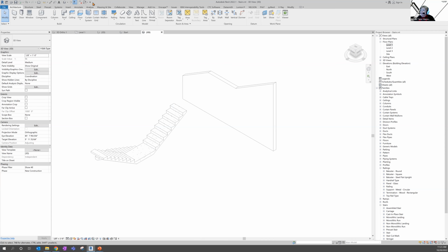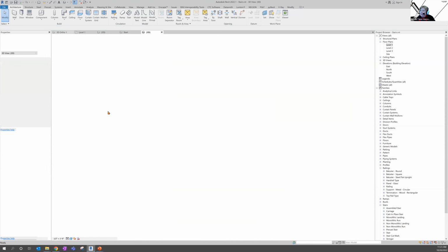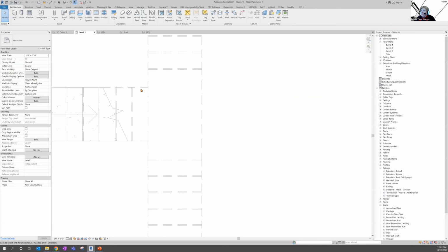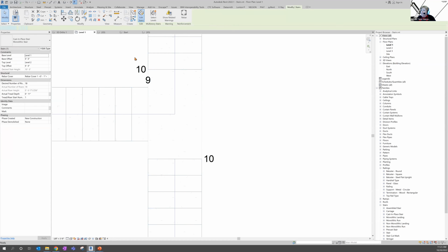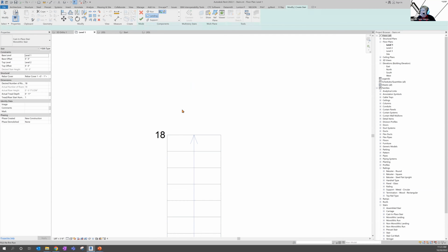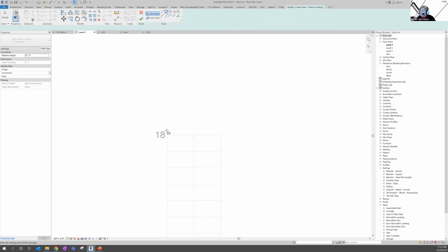That's so simple. But now let's go back to that and look at doing the landing on, not that view, this view. So if I pick the stair, and this one does have a tuck in underneath it, so it's not flush right there. Do I take the stair and say edit stairs? And now I want to do the landing on it, and sketch in rectangle. Bada bing, bada boom. Yeah, we're going to go with that.